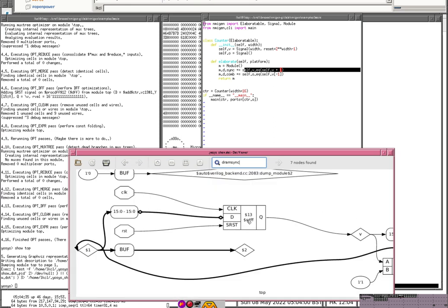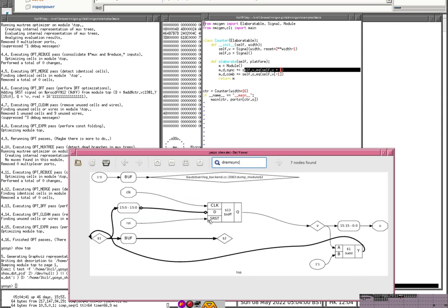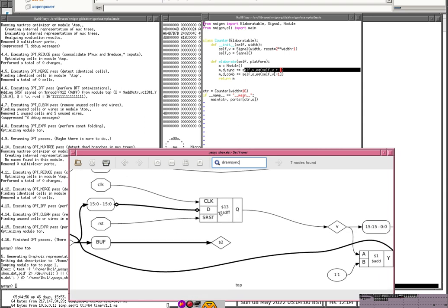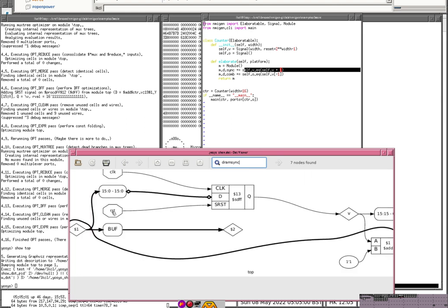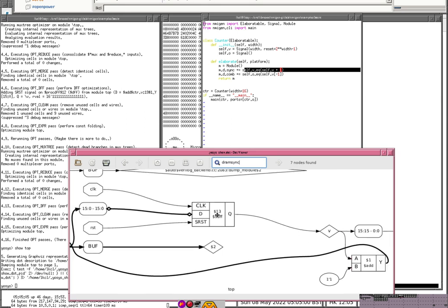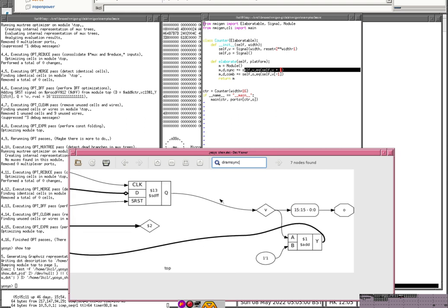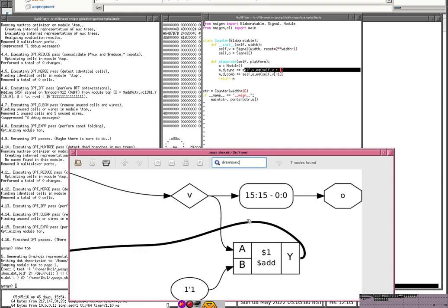And we should see, yeah, there we go. It's been turned into a D flip-flop. Okay. Right. So this starts to get closer to what would end up on your FPGA or in your actual VLSI ASIC. So you've still got the clock. You've got that D flip-flop which stores your v, and there should be a reset value. Yeah, there we go, there's a reset going into that. There's the v, and there's still the output O of the top bit 15.